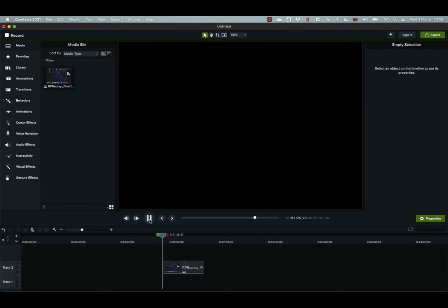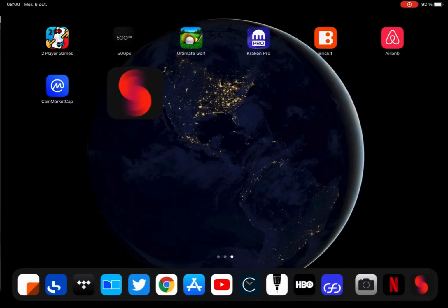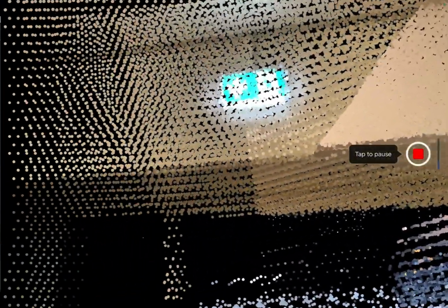It's a small app that you can find on your famous app store. The one I used is Sidescape because it's quite handy. It can export automatically E57 format. So what you do here, it's an iPad Pro. I'm just scanning the office by basically looking at it through the camera. So you see it's like a beam of points going to the objects and recording the positions of everything. So you go through until you reach the max capability of the tool, of this app.